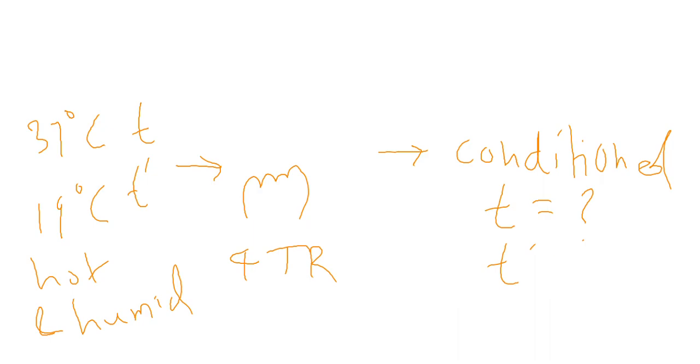We are also interested in knowing its wet bulb temperature. So let us call this state 2, with T2 dash and T2, and let us call the incoming air state 1. We will also have another piece of information: this coil is at a surface temperature of 5 degrees centigrade. So how do you describe this process on the psychrometric chart?